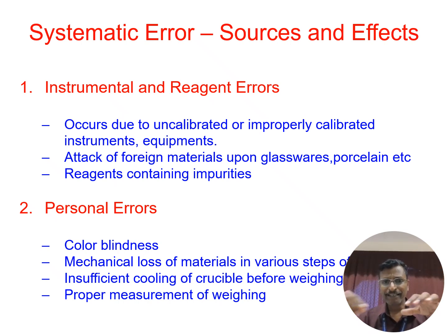Okay, for the closed container, you have to wear gloves and a mask, everything. Then take the sample, even graphene oxide or CNT, and transfer it into the butter paper or whatever you want to use. Close the door properly and wait for some time, because while the weight is fluctuating, don't take it. Wait for some time, and then note down the value. So these are all the basic things you should consider for the measurement.